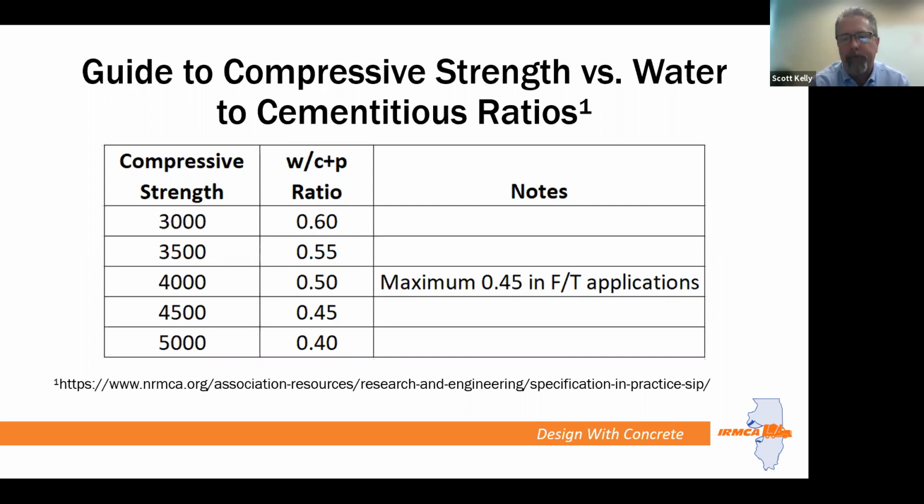What this does is basically require a producer to supply a 5,000 PSI mixture, which could cause placeability issues and obviously have cost implications. We're sure that there's more than likely a driving factor here, such as reducing permeability, as one example. But our question to you is why not specify a limit on permeability? It's likely that approach would provide a much more cost-effective mixture and ultimately would provide a known result instead of an assumed outcome.